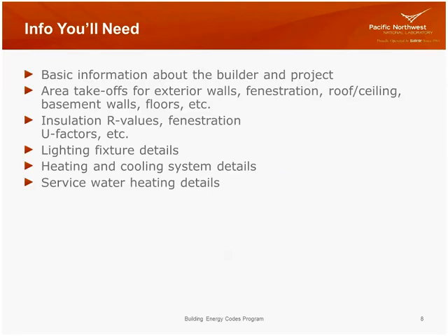So what is the information that you need to have in front of you? Before you even get started, you need to have your takeoffs. And what does that mean? You've got to have the building plans in front of you, or at one point be looking at the building plans and doing your takeoffs and having the whole summary of your takeoffs on a piece of paper or a spreadsheet. You also need to have the insulation R values, the fenestration U factors, and solar heat gain. You need to have those values, and those typically come from your specs that are based off the plans, or they could be on the plans.